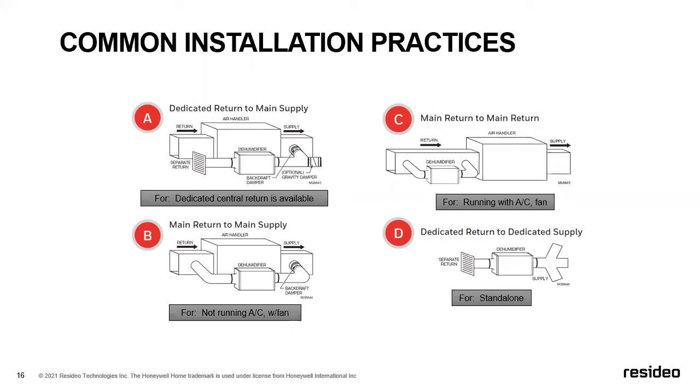If the answer to that is yes, that's where we stop and say, okay, we need to lock that dehumidifier out because the dehumidifier is not doing anything when the air handling unit is running. Most likely that static is higher than the dehumidifier blower can handle, so we're just not moving any air. Therefore, of course, that dehumidifier is not going to be dehumidifying. And we could also have some mechanical failure, over temp on the compressor if we're not moving any air.